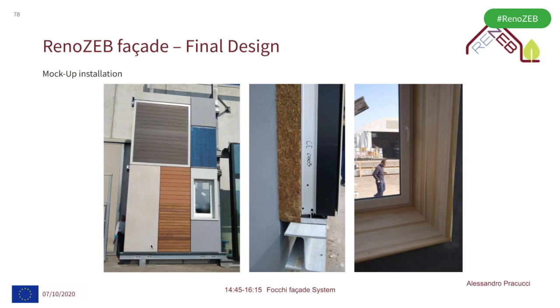External finishings are possibilities, but we have focused also on these elements because the nearly-zero standard needs to improve the thermal performance in the first moment of the building. And here you can see the existing envelope, the cavity where we position mineral wool and the panel. Here the intrados. The new intrados remains the only activity to be conducted on site after the installation of the facade.